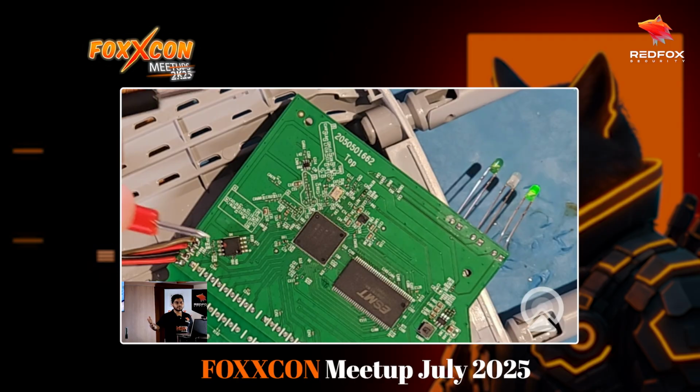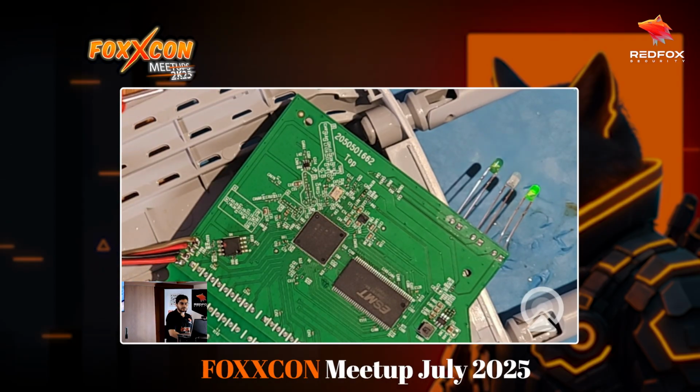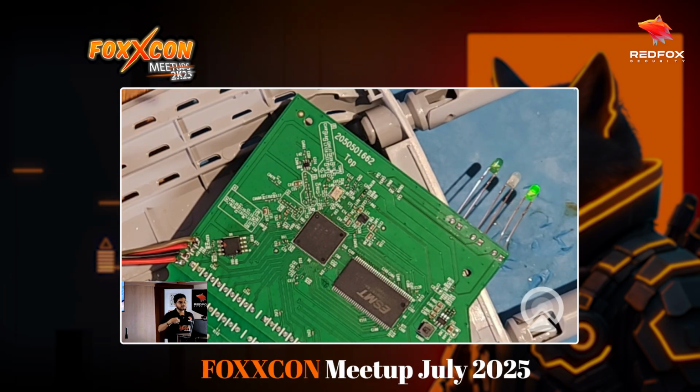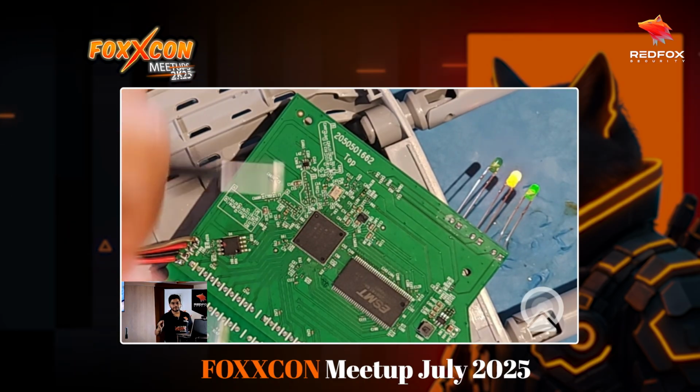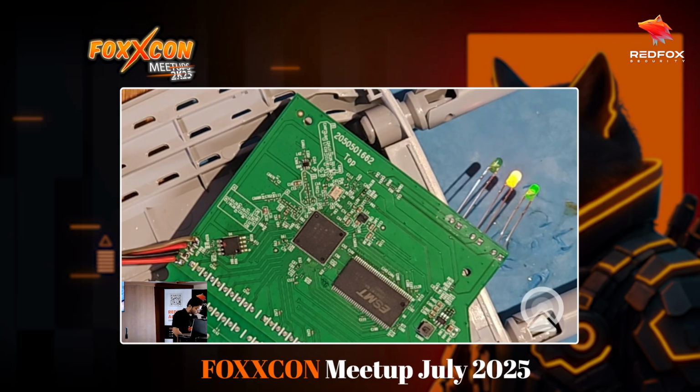Because it is transmitting data, the voltage is fluctuating. That is how you'll be able to figure it out manually here. Then, as I said, the other pin will receive information, so it should not show any voltage whatsoever. And as you saw, one pin was not showing any voltage whatsoever. That's why we are now pretty much sure which cable is what.